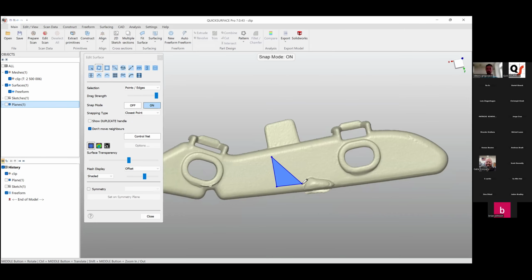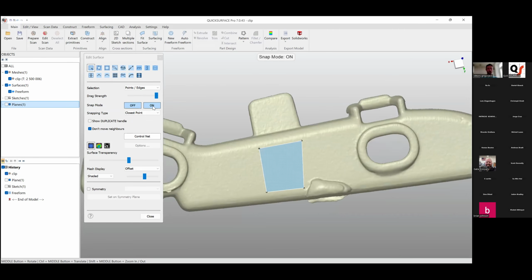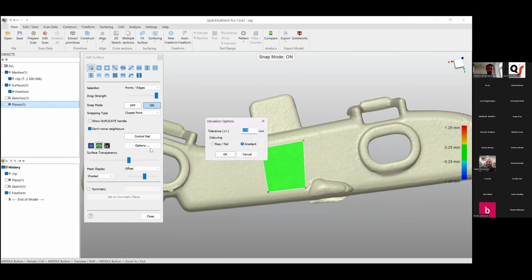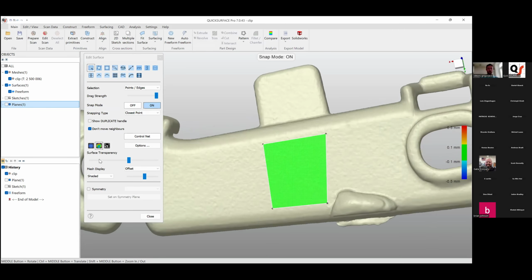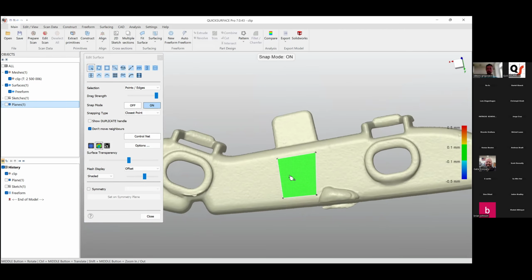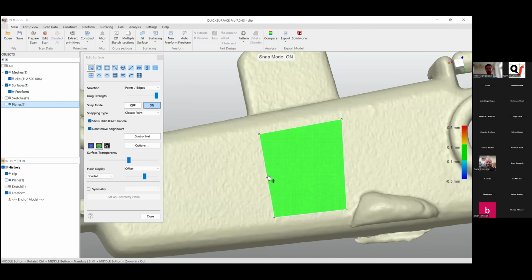Let's start with creating the first quad. We can switch on the tolerance display and set it to something a bit finer. From this point, we can start to expand this. By default in the software, you will see this D button if you select your edge. So you can come over to this edge and press the D button, and this will automatically let you create another quad.